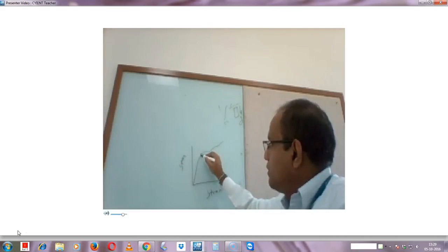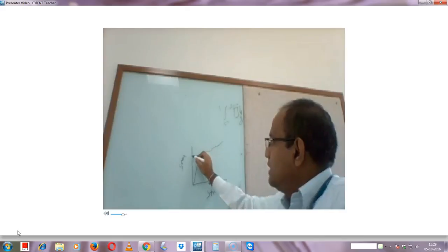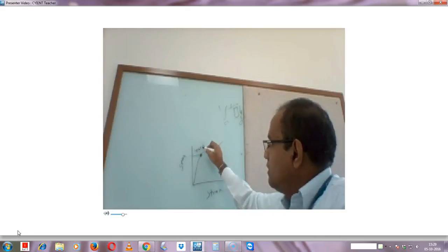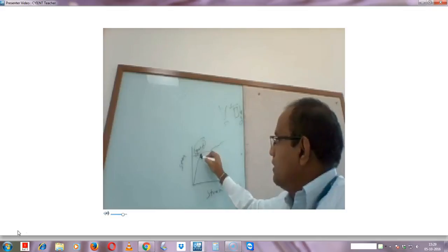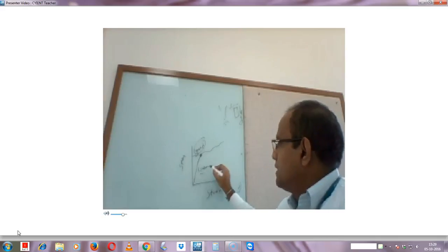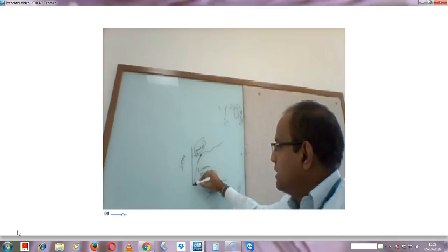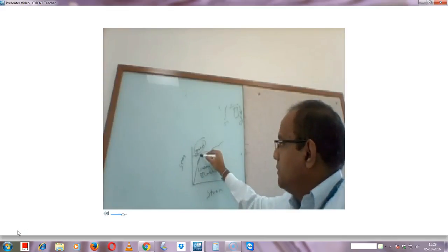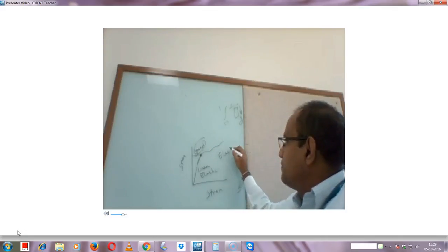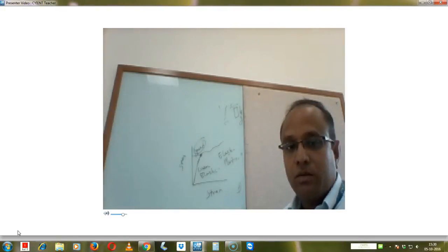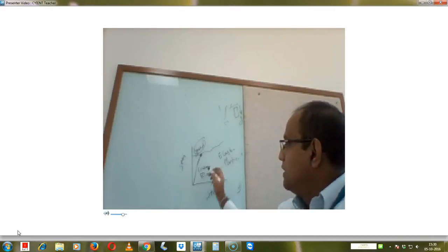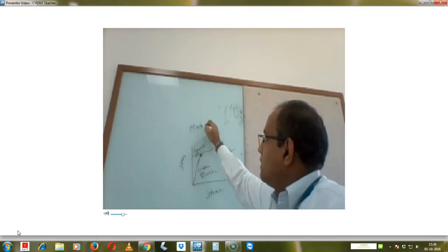If our load application causes stresses below the yield, then it's a linear analysis. Elastic, we can say. We perform only elastic analysis. Suppose because of load application the stresses exceed beyond yield, then we need to go for elastoplastic analysis. This will be the material nonlinearity.